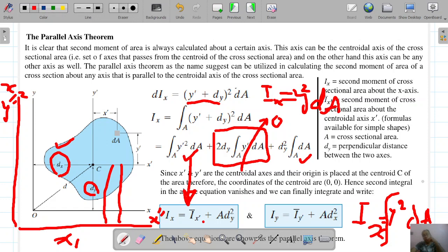you will not be able to bend it. The reason is this: when you were applying the bending before, its second moment of area was very low, and when the second moment of area is low, the bending will be very great. But in the other case, in which it was standing perpendicular to the base of the table, the second moment of area is increased. So when the numericals come, and in the class, I will also show you practically how it can be done.